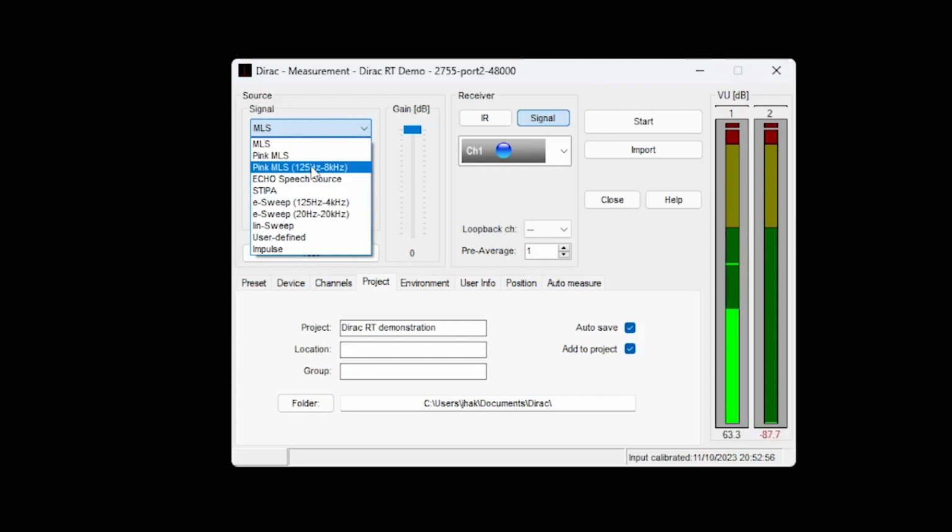In general, even if a band-limited stimulus would do, as a rule of thumb, if there is no reason to use a band-limited stimulus, use the wideband version, as the wideband stimulus bears more information, which may be useful for future analysis. In case of the pink MLS stimulus, the reason for band limitation would be that you need as much of the available power from your amplifier as possible and don't want to waste any power on sound outside the frequency band of interest.